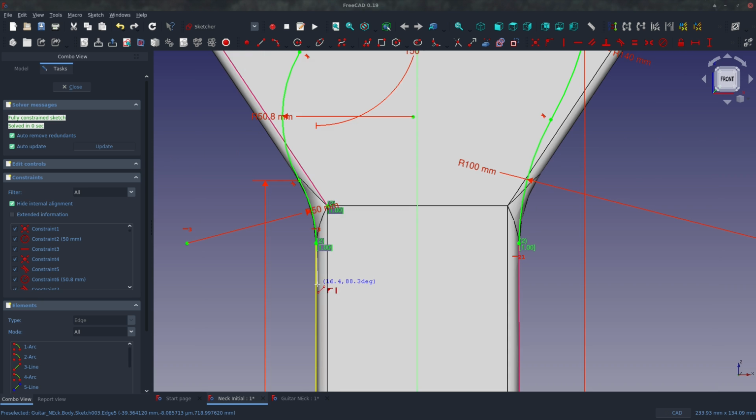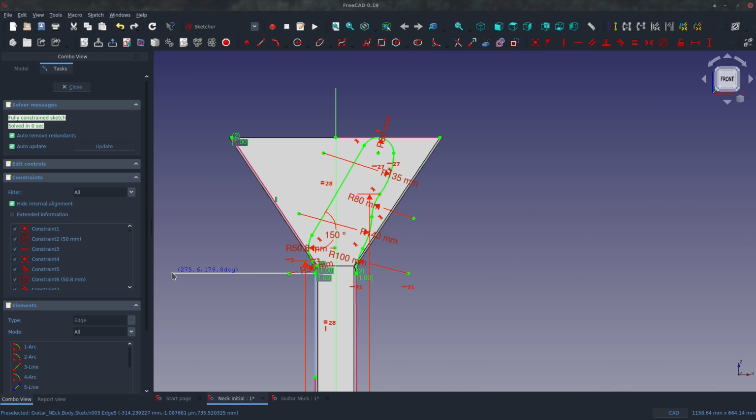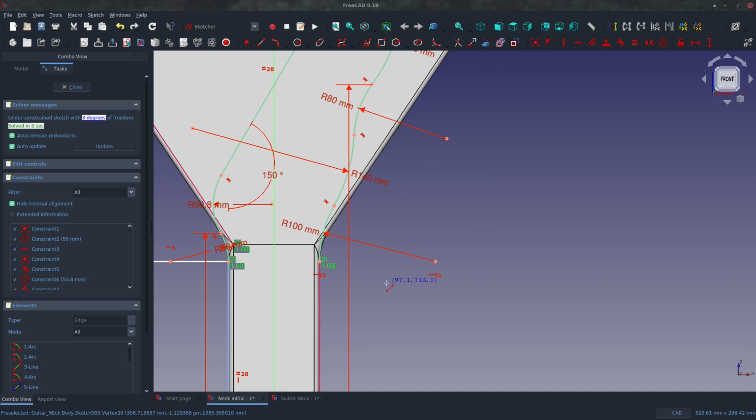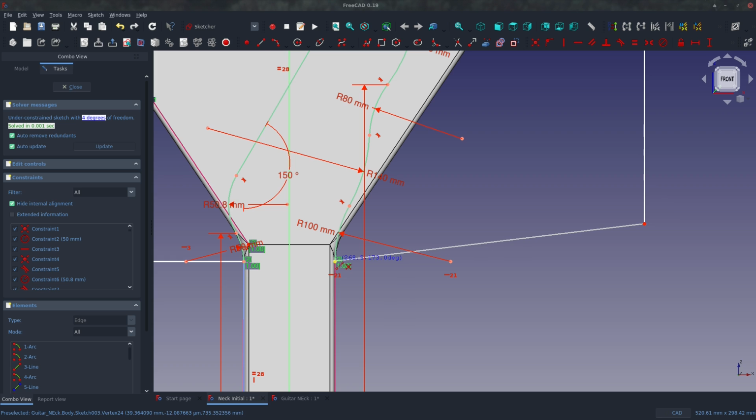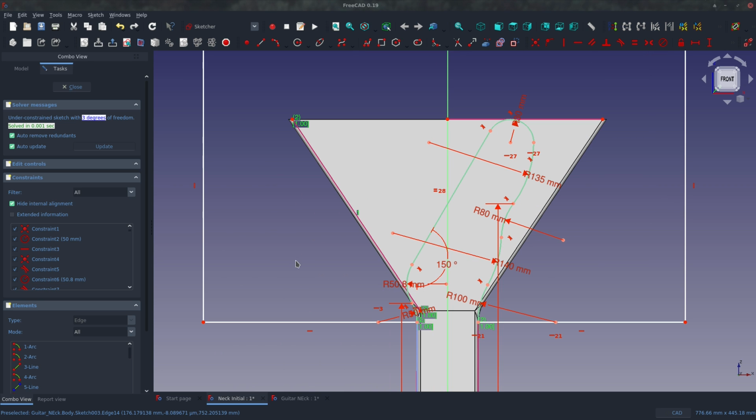Now you can do a Boolean here, right? There are many options. Now, I think a lot of people will look at what I'm doing as not polished, but if I were to just close this sketch off here and do something like a flip side to cut, which is available in other platforms, I'm running a very similar operation in other platforms to what I'm running in FreeCAD. So I don't think it's too onerous what I'm doing.